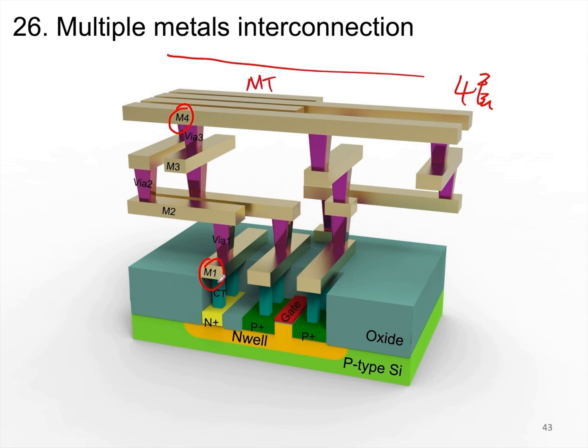Metal connects through this contact to the body and drain region. Showing the oxide completely, it looks like this. The oxide, like glass, is somewhat transparent. This is our interconnect, with oxide between them. The oxide extends all the way up here. To show the metal structure, we hid the oxide above. Using this 3D structure, we demonstrated PMOS transistor processing and layout usage.